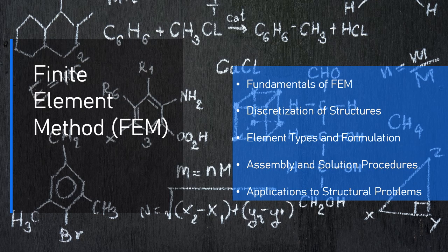2. Frame analysis. For frame structures, which consist of beams and columns, FEM allows the calculation of axial forces, bending moments, shear forces, and deflections throughout the structure. This is important for multi-story buildings, bridges, and industrial structures. Application example: a high-rise building with wind or seismic loads.